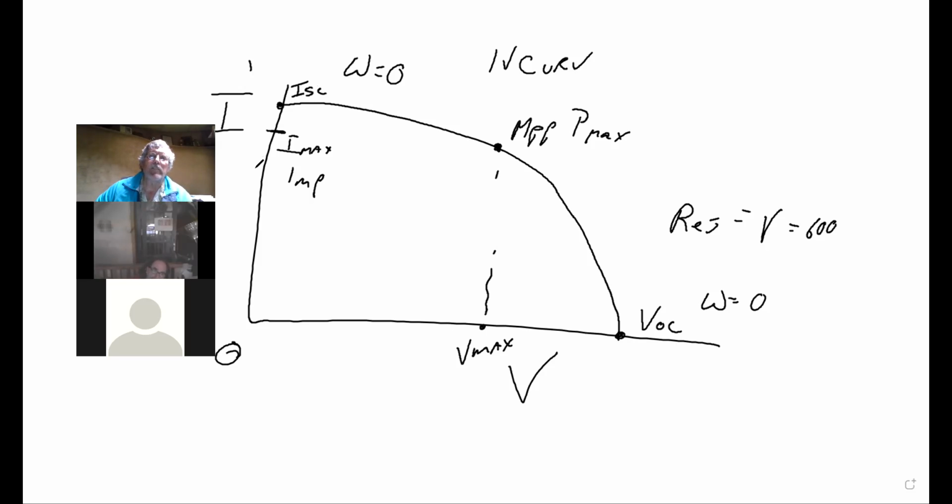So when you short a panel out, it's not producing power. In order to measure amps, you have to have current flowing, right? Well, yes. And with no pressure, no volts, no flow, I think you could measure somewhere close to ISC, but never actually at ISC, because you'd have 0 amps or 0 watts. So the other question is, if you short a panel out, it's not going to burn itself up.